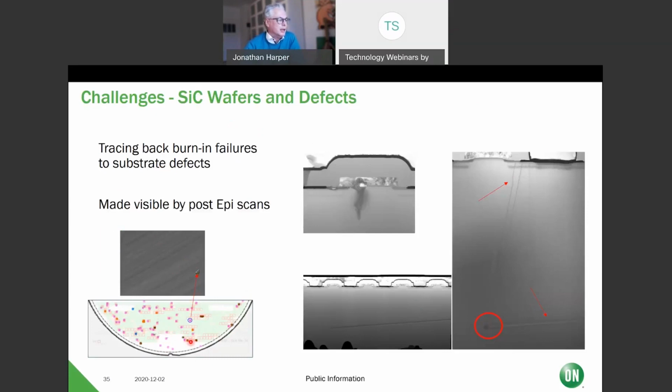The first thing is you get defects in the SiC crystal structure. This is something to do with the fact that this is not 90 degrees in the SiC crystal structure. This is slightly shifted. You can probably see a little bit here. You slightly shifted, and this means that cracks will propagate, and they're very difficult to detect. So if you made a chip with it, it would work properly, and then after a while it would fail. And then there are other things like the difference between the SiC and the silicon dioxide, the gate oxide.